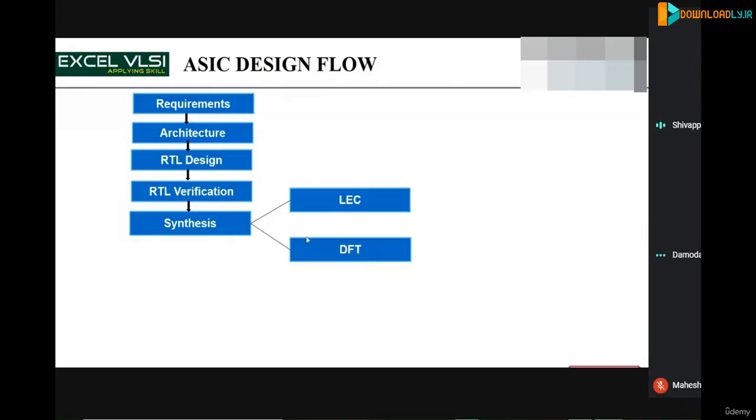After synthesis, there are steps where we include some structures in order to test the chip once the chip is out. Scan insertion, ATPG, all this comes in the DFT process. And pre-layout STA, this is where, before we do the layout, we do the static timing analysis.